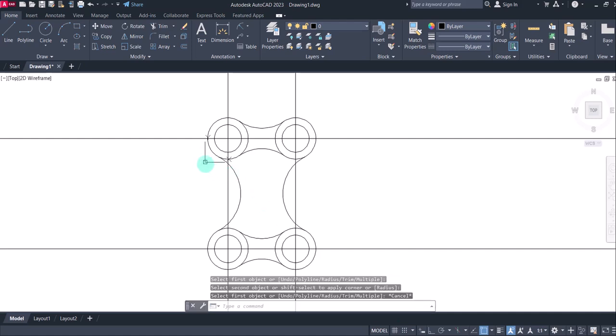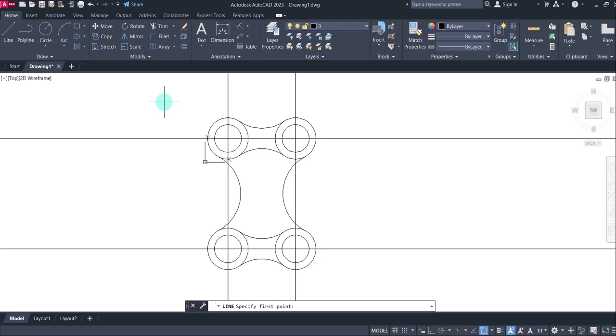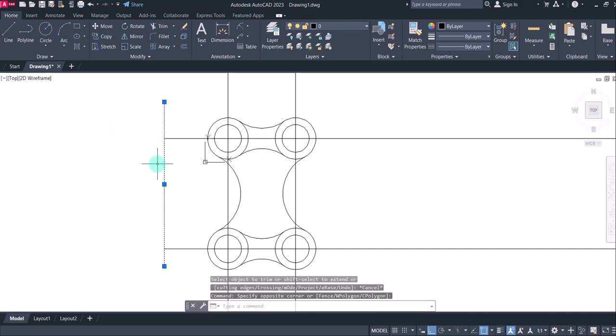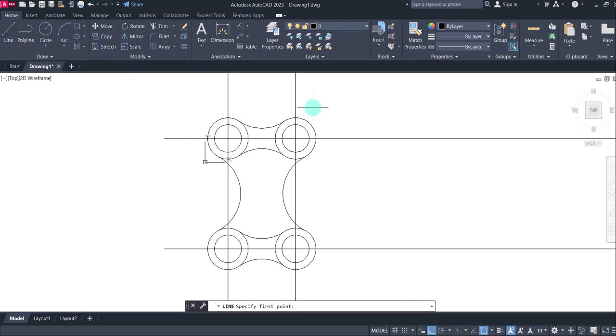Okay, so how am I going to do that? I'm going to create an intersection for these lines so I can cut it off. Okay, let me turn on my auto. Okay, then trim. I'm using trim to get this place off. Trim. Okay, then I can delete the line. I'm done with this line. The line is just to create an intersection.